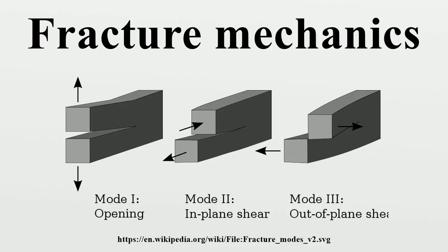Fracture toughness test limitations: a problem arose for the NRL researchers because naval materials, e.g., ship plate steel, are not perfectly elastic but undergo significant plastic deformation at the tip of a crack. One basic assumption in Irwin's linear elastic fracture mechanics is small-scale yielding, the condition that the size of the plastic zone is small compared to the crack length.